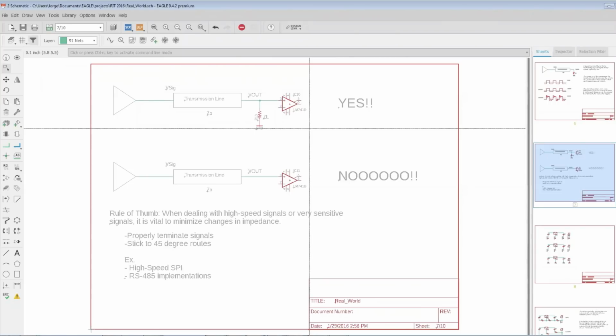You have to be very careful with the word ground in signal integrity. And really, you always should be. But once you're dealing with high frequency signals, the understanding of ground needs to change a little bit, and we need to expand on it, become a little bit more nuanced and more specific with it.